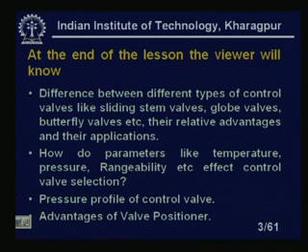Advantage of the valve positioners, as I told you, this is an accessory. So, what is the advantage? The valve positioner is an accessory to the control valve. Actually, it is installed fixed to the control valve itself. That means the pneumatic control signal will not come directly to the control valve, it will first come to the valve positioner. The valve positioner will make some additional control signals, which will correct according to the positions, and those signals will go to the diaphragm of the control valve. The diaphragm, all these things we have studied in detail in lesson 38.